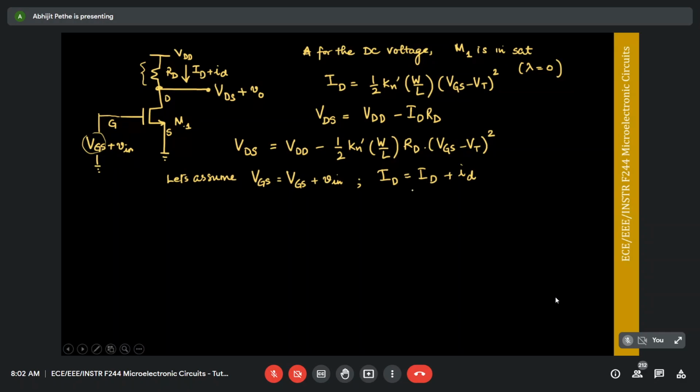Second thing, remember, we are dealing only with linear systems, so there's no distortion. When I say no distortion, it essentially means that if I give a signal with a fixed frequency as the input, the output will have the same frequency as the input. So we are not going to worry about change of frequencies. There are different circuits which can do that, but we learn that later in ADVD. So for now in this class, if I'm giving a 60 hertz signal at the input, I will get a 60 hertz signal at the output. The current will have a frequency of 60 hertz.